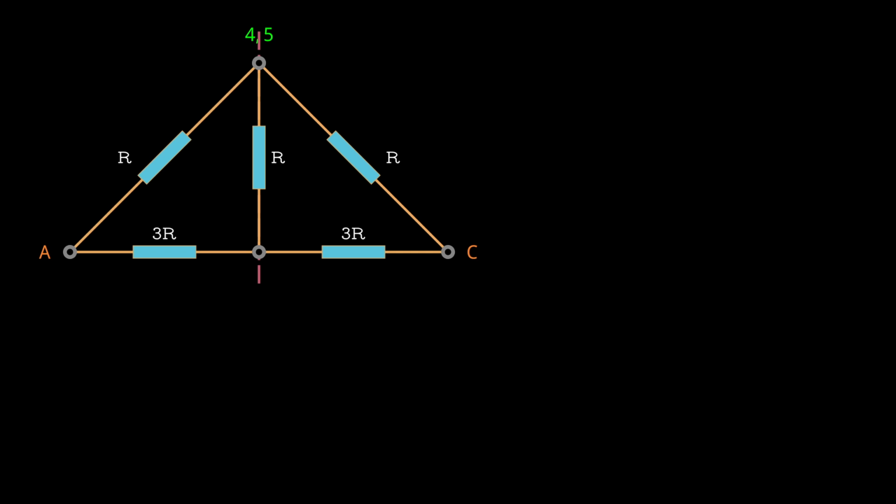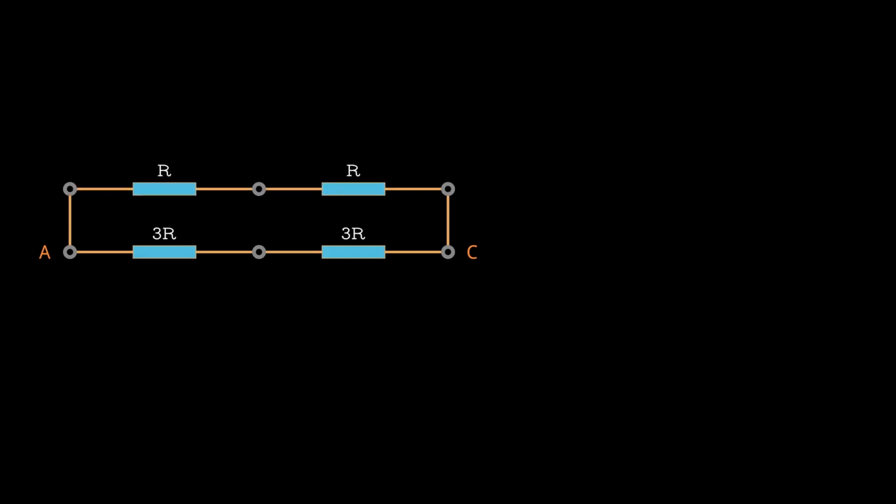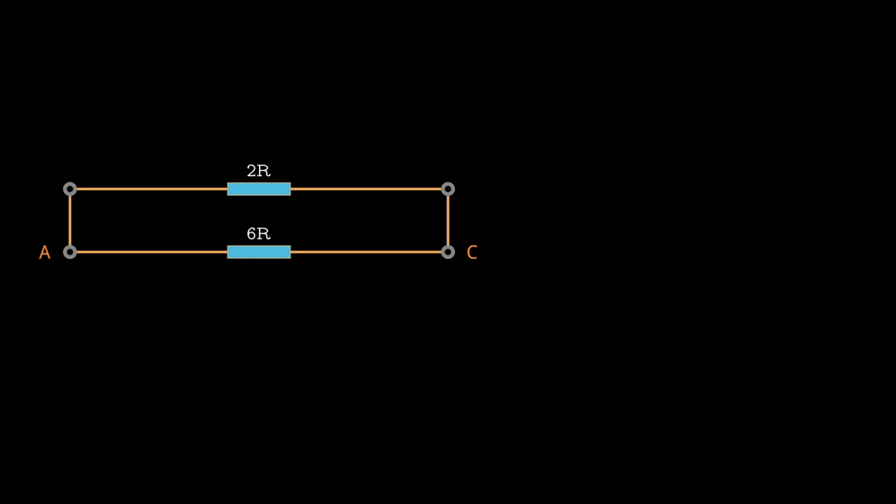While we could have made this simplification from the beginning, I wanted to demonstrate the reasoning behind it, rather than just following instructions blindly. I hope this approach helps you understand more clearly why this simplification is possible. We'll remove this resistor and proceed by simplifying the circuit, replacing the remaining series and parallel resistors with their equivalent resistances. Step by step, we can work through each simplification to find the equivalent resistance between nodes A and C.